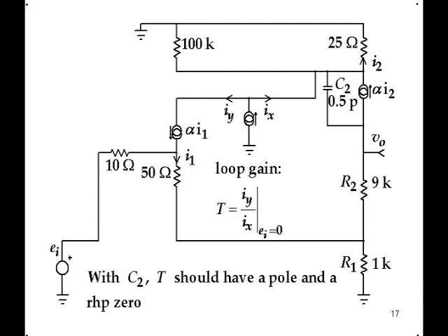So you'll get a large inverting gain at low frequencies from the second stage, and there will be a fairly low frequency pole caused by the C2. But as frequency approaches infinity, the C2 is going to look like a short. And so the gain is going to flatten out at a much lower value than it was at low frequencies, but it's going to be a non-inverting low value of gain towards infinite frequency.